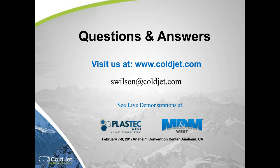The positive side is it's good that it doesn't take the pitting off. Because if it took the pitting off, I just profiled that steel. I dimensionally altered that steel by just a few thousandths. If my process was capable of doing that, we don't want to do it on cavities and vents, because now I will cause you to have flash. I'll be wearing out your parting lines and your shutoffs and your cavities, but it's too soft. So the bitter and the sweet of it is, yes, it'll take surface rust off, but it won't get the pitting off. It's not aggressive enough to do that. But actually, that's a benefit for us.